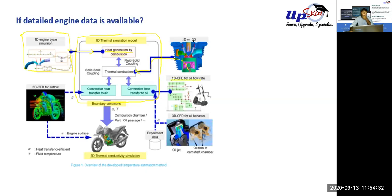A 3D CAE analysis, like a thermal conductivity analysis, can be used to find that out. We can do 1D CFD for the flow rate. For example, this is an oil engine, so they're considering oil flow rate, but if it's a liquid cooled engine, then we can consider the flow rate for the coolant. Similarly, we can consider the flow rate for the airflow in the radiator.